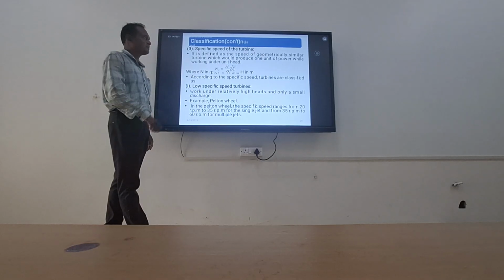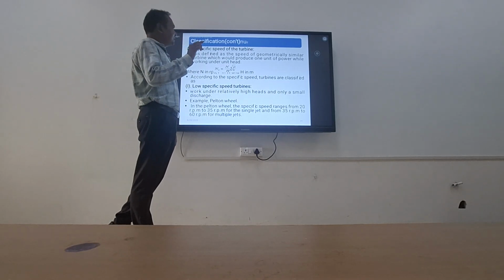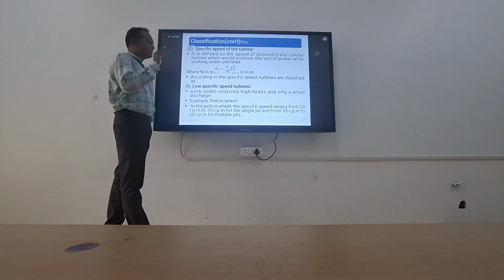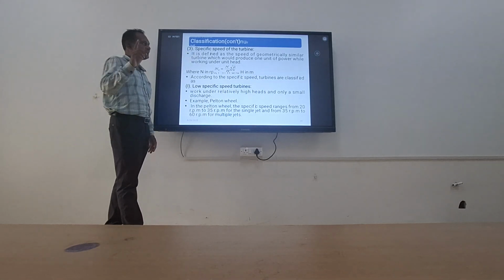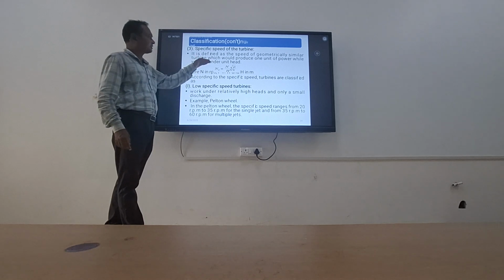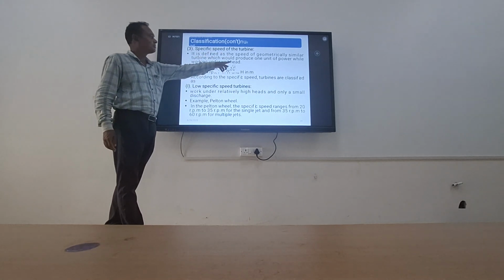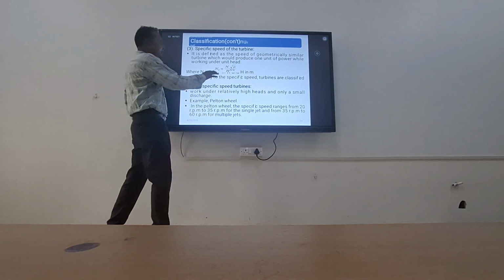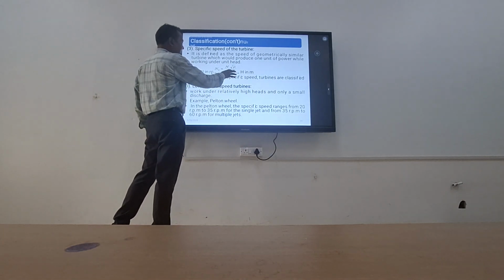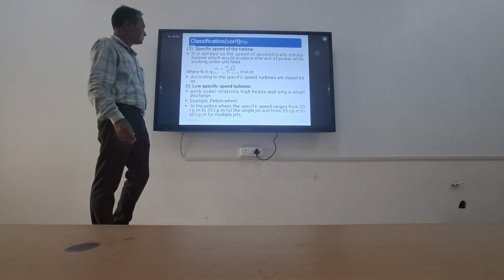The formula is Ns = N√P / H^(5/4), where N is the RPM, H is the head, and P is the power.